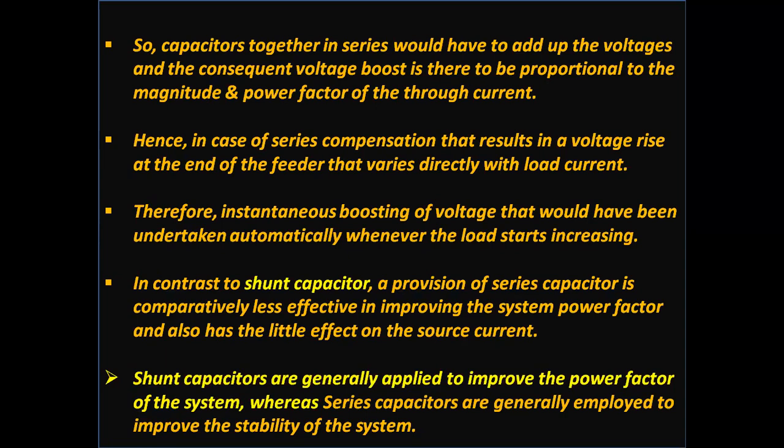Hence, in case of series compensation, that results in a voltage rise at the end of the feeder that varies directly with load current. Therefore, instantaneous boosting of voltage that would have been undertaken automatically whenever the load starts increasing.